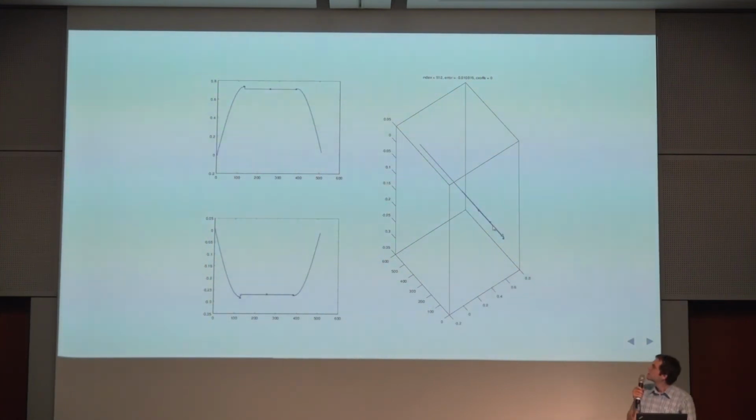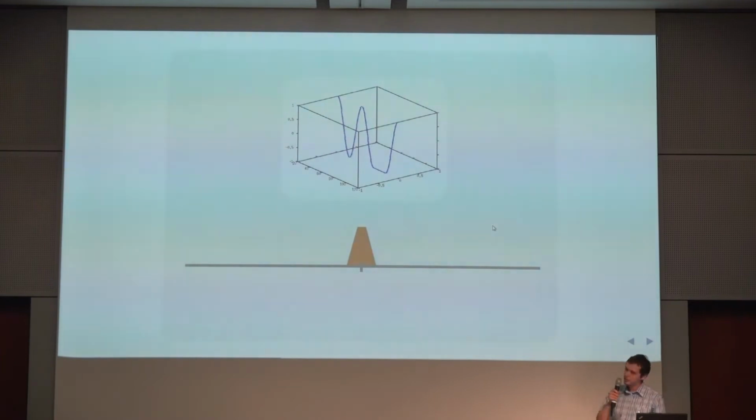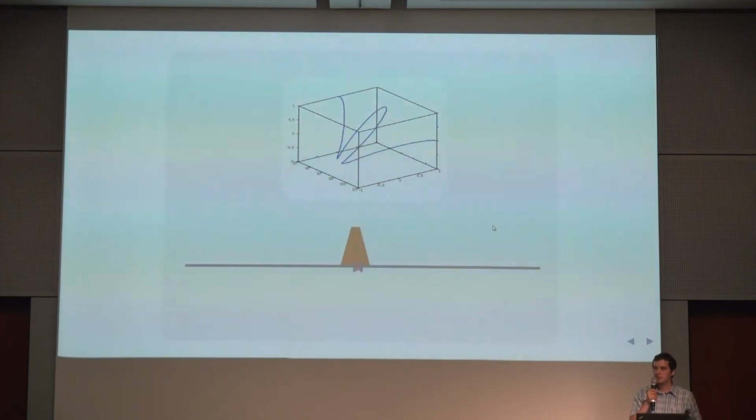Okay, so what other problem can we face while doing this BPSK31 demodulation? The other problem is frequency difference between the transmitter and the receiver LO. So, for example, if we don't tune very precisely with the receiver, then we get something like this at the baseband.